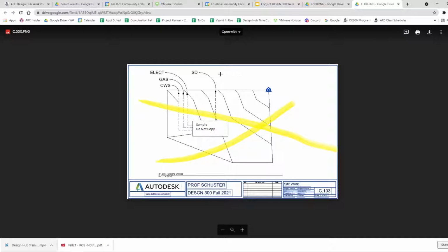So somehow from the street over here, there are connections to the public or private utilities that you need to put your own pipes in, underground usually, to get that utility to the building. And these are very common abbreviations. CWS would be cold water supply. How do you get water to your building, and then usually from the building to the landscape? How do you get gas? Almost every building has a gas connection, even if it's not used.